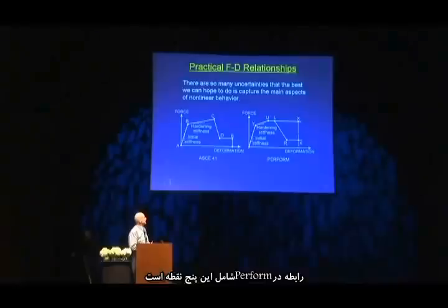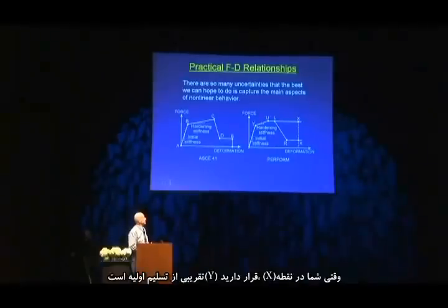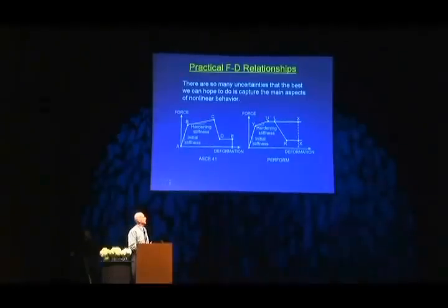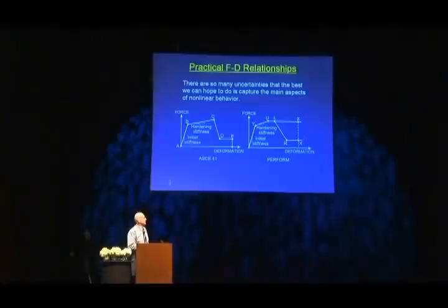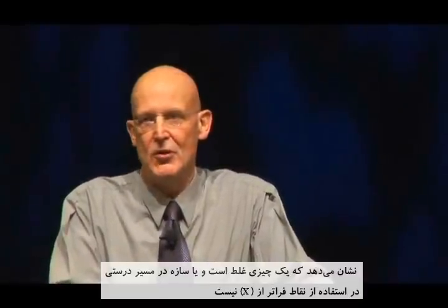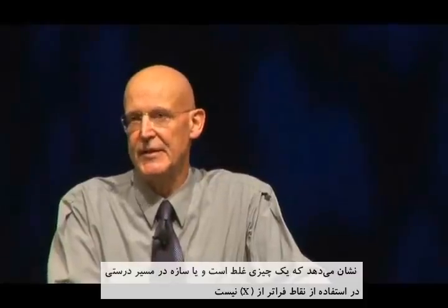And PERFORM has these 5 points, Y, U, L, R, X. Y is an estimate of the initial yield. Then U is where you reach the ultimate strength. L is the ductile limit, and then strength loss down to R, residual. And point X out here, typically you'll specify that to be some fairly large value, such that if you ever get out that far, you'll say, well, something has gone wrong or the structure isn't right. There really isn't any point in continuing beyond point X.